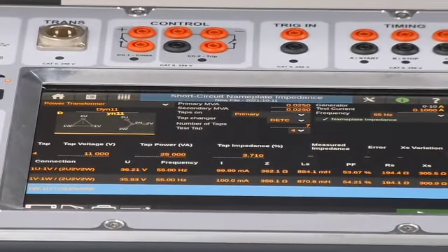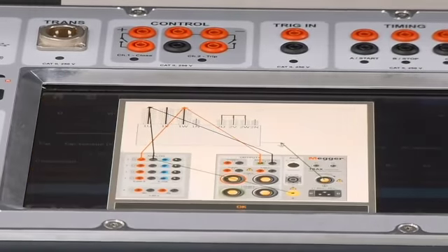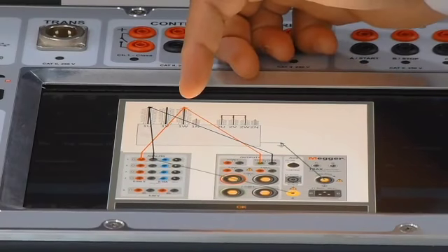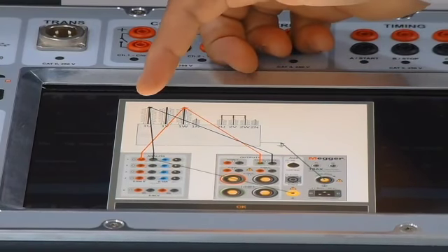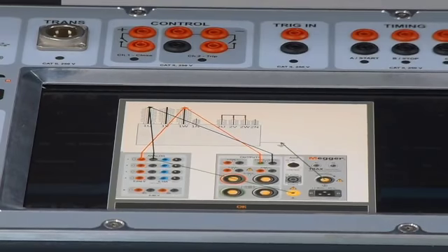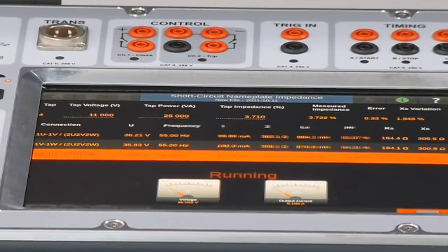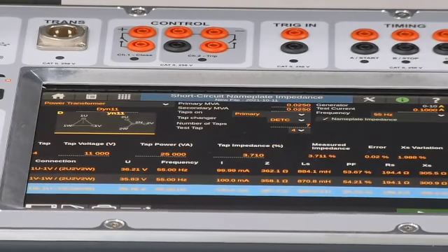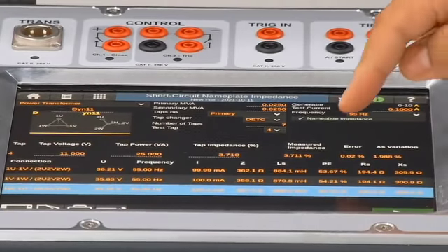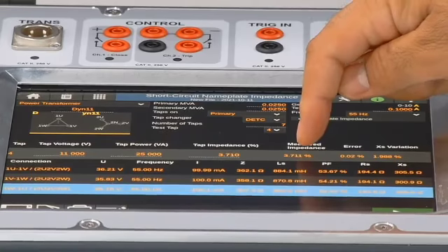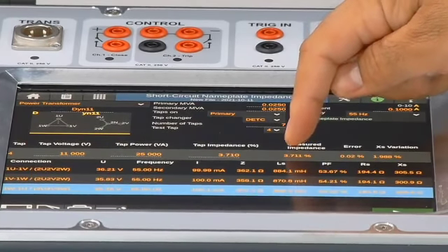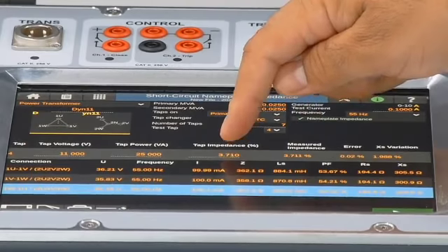So on my cards, I can just click again question mark and show you now we are connecting between W to U phase. And I'll click OK. I confirm this connection. I will start injecting. So now my third phase shows up, and now we could calculate the measured impedance for the three phase, which is almost same as 3.7.